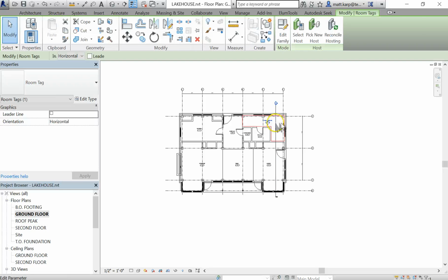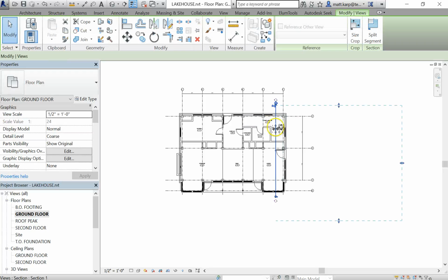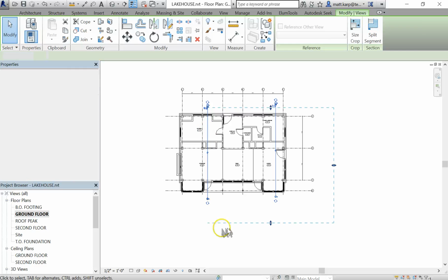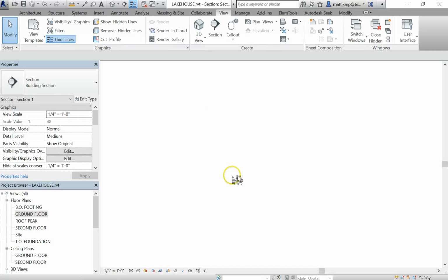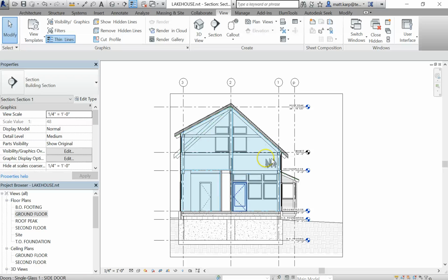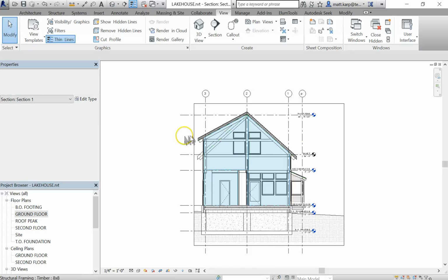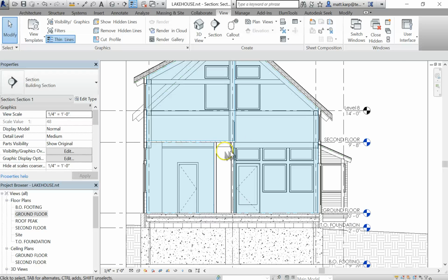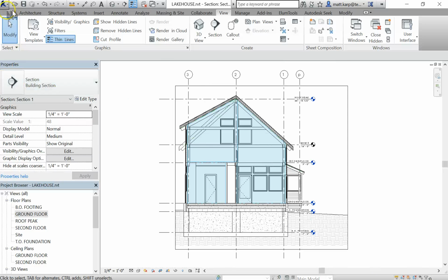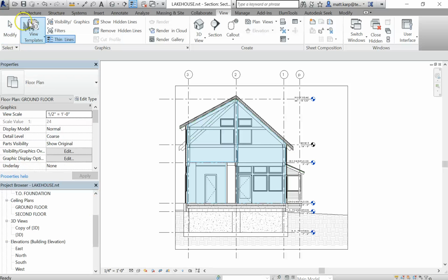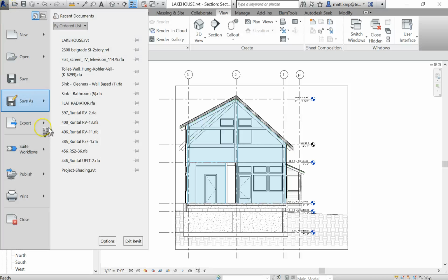just move that section you've already configured to show the interior fill of the rooms to wherever it needs to be, so that you can check it again, make sure all these new rooms you're cutting through are going through. I'm ignoring interior closets right now because that won't really matter. The overall building use in a closet is not a conditioned space. So with that, what we're going to do now is export to an XML file.